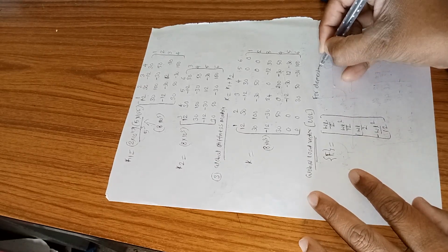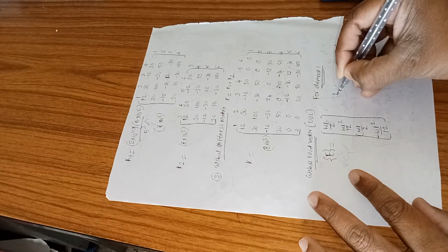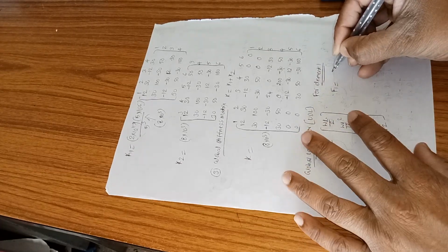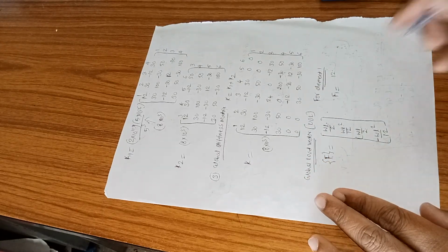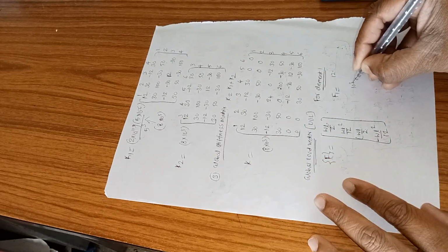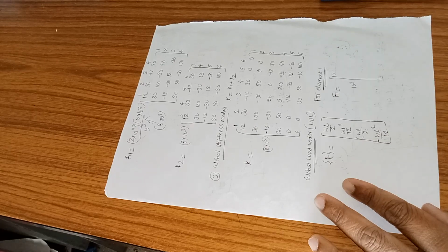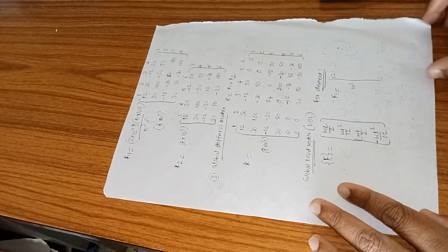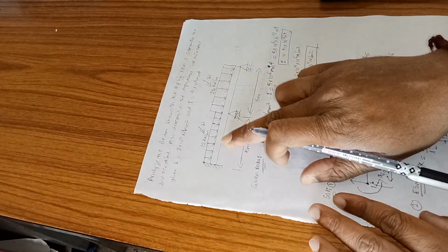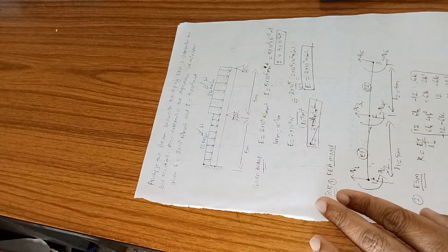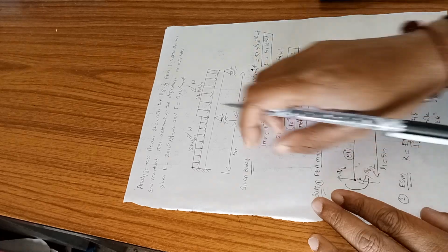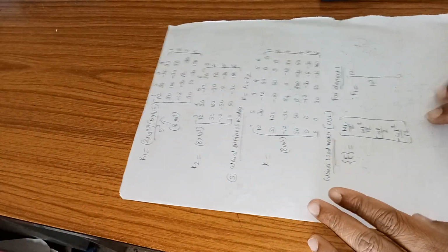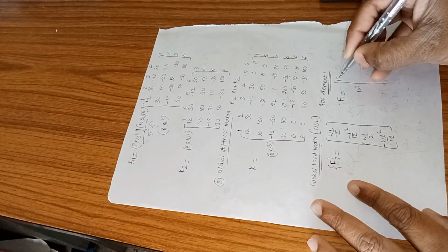when I'm trying to write, I'm going to write F1 is equal to 12 into 10 to the power of 3. So 10 to the power of 3 is common everywhere, so I'm just going to write the 10 to the power of 3 outside. So 12 into 10 to the power of 3. And one more thing you have to observe here, the load is acting downwards. So whenever the load is acting downwards, always take the load value as minus. Whenever it is acting in the top direction, consider it as positive. So here it is acting in the downward direction, so let me consider it as negative.